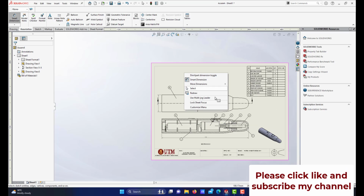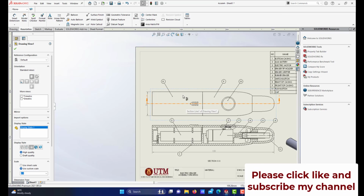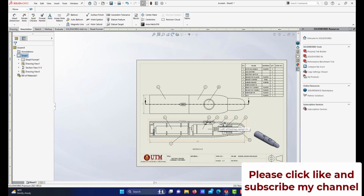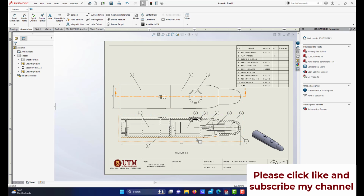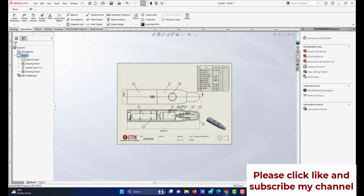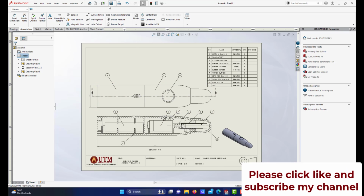Let me terminate this dimension mode. I do some adjustment since I need to drag this dimension a little bit to this position. All right, so we have the overall size. So at least when people read the drawing, they know what's the overall size. Let me move here like this. All right, so this would be the finalized version of my assembly drawing. All right, so let me save my file again.